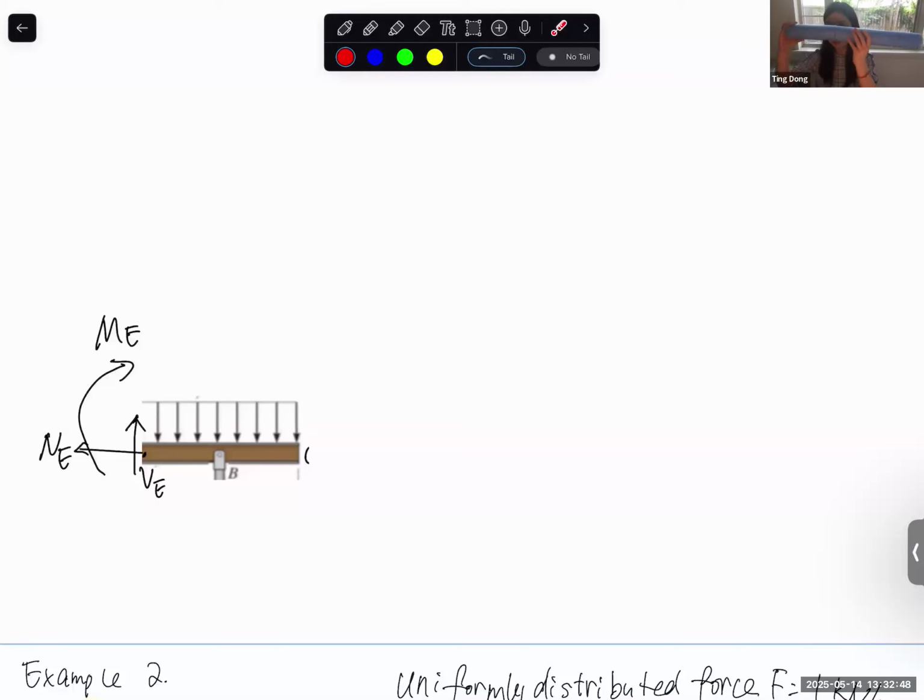But on this side, cutting through the same point, when I choose this side, and this is the cutting surface, for tension, the internal force should be in this direction. Make sense or not? So on different surfaces, cutting through the same point, on the positive or negative surface, tension generates an internal force that on this one should point to this direction, and on this one should point towards this direction.